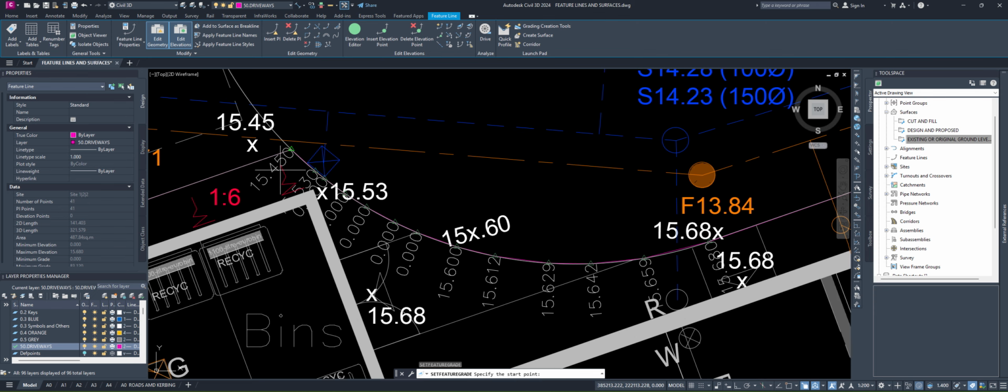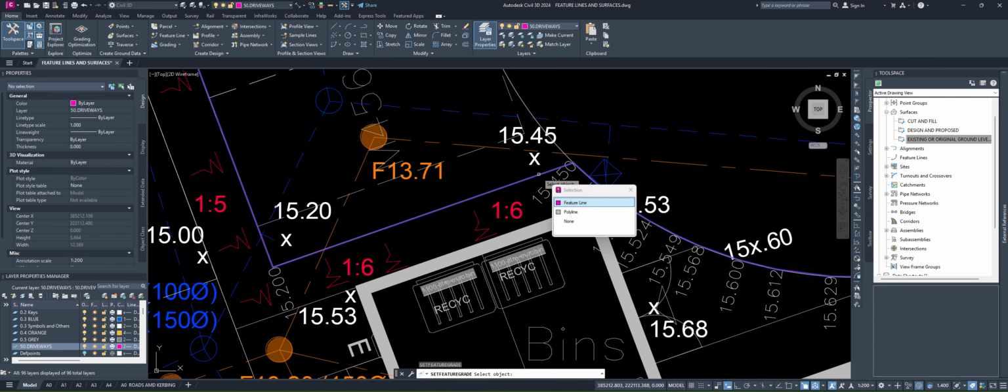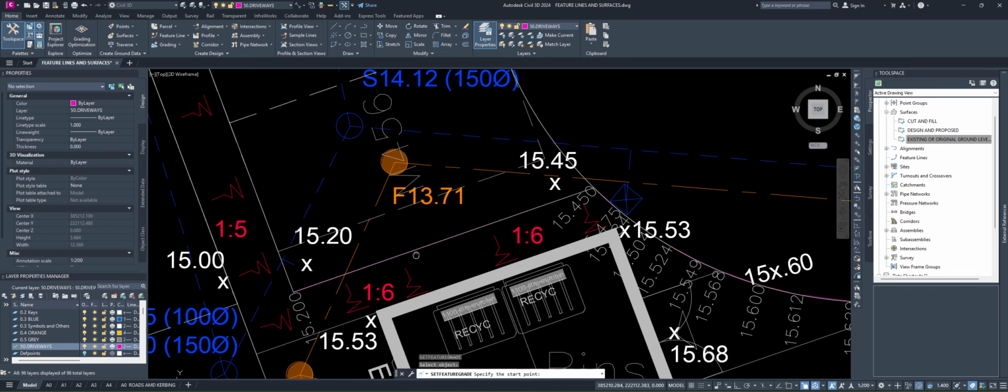We're gonna repeat exactly the same process with the next few points where we have any levels applied. So I may literally click up on top of that level or up on top of that level. I'm gonna just slide down to my next available point with level. I'm gonna click OK, and now it's gonna regrade the levels on all the points between this point and that point. Let's click enter to complete the regrading, and one more time to refresh the labels. Okay, now let's click again to repeat the command to get again into our set grade function.